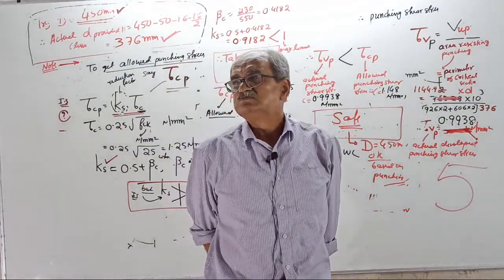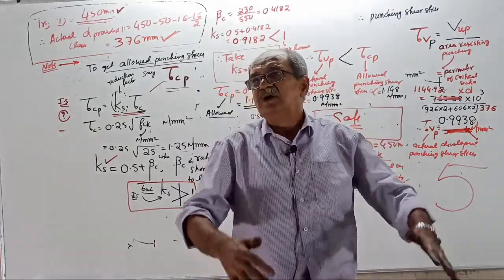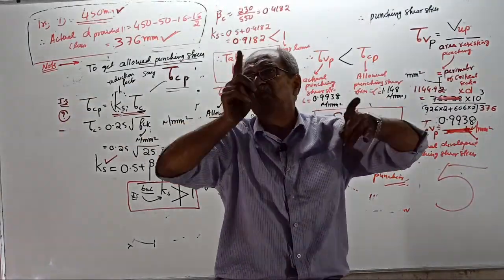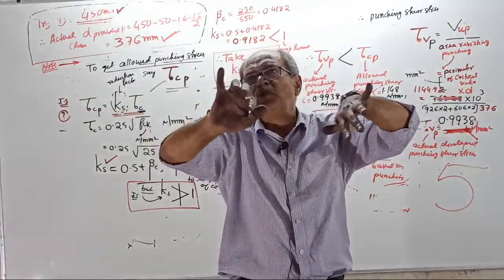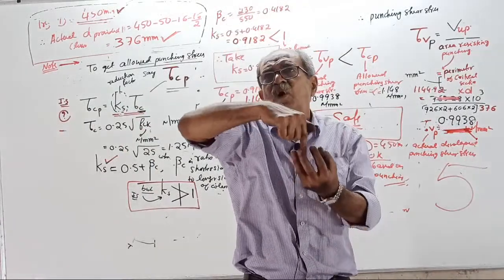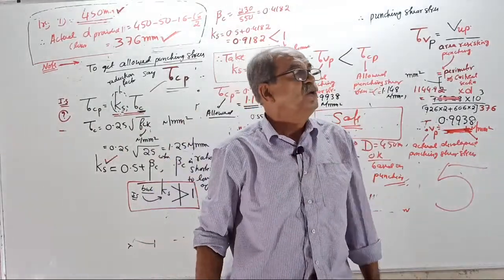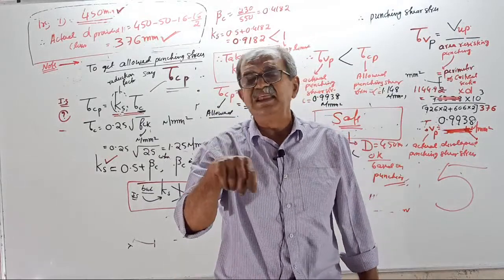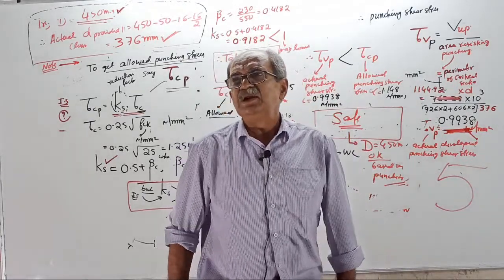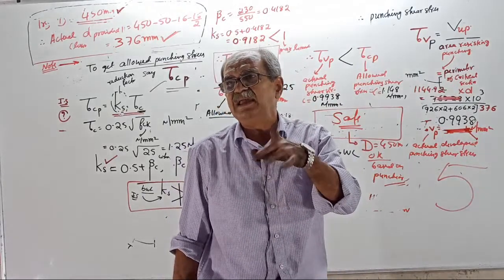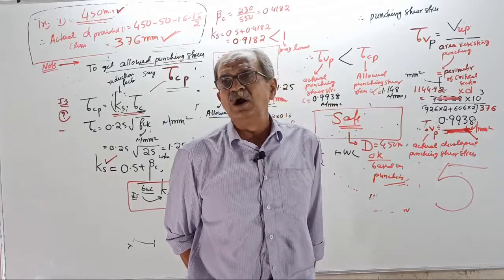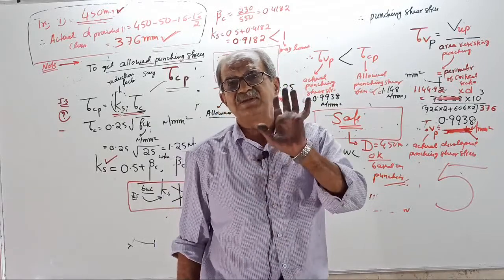Benefit number 2, when you increase the depth, your critical section will move further outward. When it moves further outward, punching force will become lesser because column load minus higher contact area. Punching load reduces, resistance increases. Therefore, double benefit. Therefore, you need not increase too much. By judgment, suppose you got around 30% over stress, you don't increase by 30%, increase by 20%, sufficient.